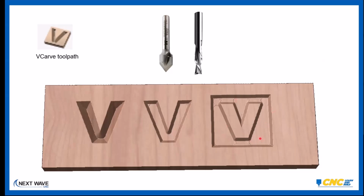Now, this last option, I call this a reverse V carving. You're still using the same V shape, but we've added a vector square around the outside of it. And when you have two vector lines like that, then the V carving toolpath goes between those. Rather than on the V, it jumps to the outside of the V. And then it'll carve in this area.